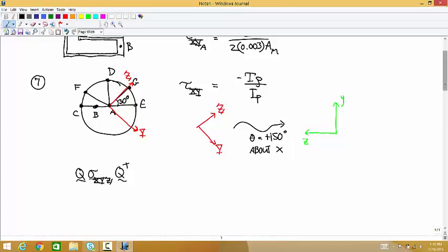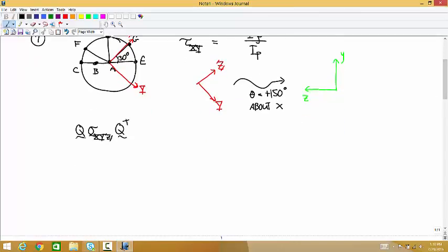And then calculate the eigenvalues, so that'll give you the true stress tensor. Then calculate the eigenvalues, that'll give you the principal stresses. So say you calculate the eigenvalues and it gives you, we'll call it stress 1, stress 2, and stress 3.